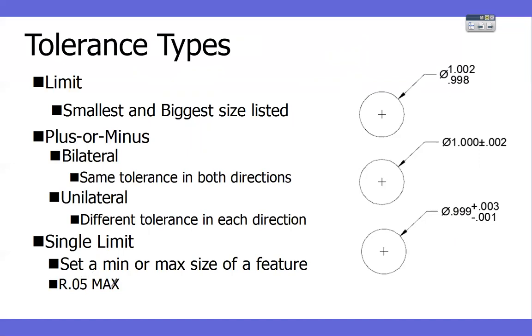So like on a casting or injection molded part, when they make the mold, they have to put some radiuses in there. If they're going to do a cast part, metal doesn't like to flow around sharp corners. It likes to flow around rounded corners. And so when they make the mold, they're going to add some radiuses to it. On that drawing, the person might say radius this max. So casting radii 0.06 max. So it tells the people making the mold, you add whatever radiuses you need, but they can't be bigger than a 1/16 of an inch.